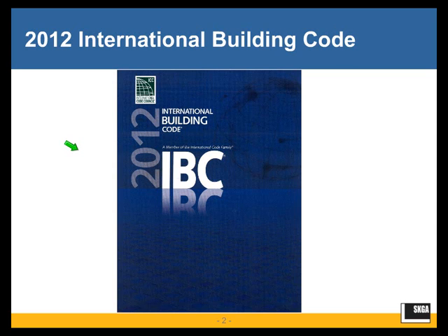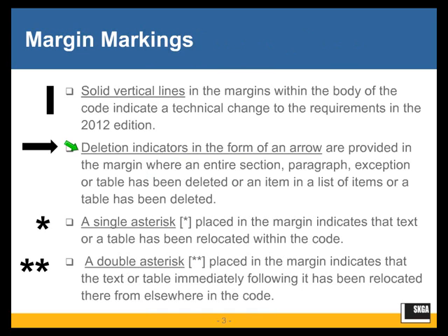This publication is something a structural engineer needs. We sometimes get the question, well, can we just use the reference standards in the IBC? Do we actually need the IBC itself? And yes, you do need the IBC most definitely for chapters 17 and 18, which don't rely on reference standards, but there are also a number of provisions in the other chapters that are different than in the reference standards, and the provisions in the IBC would take precedence and be what you need to follow. So it is important to have a copy of this accessible for your use.